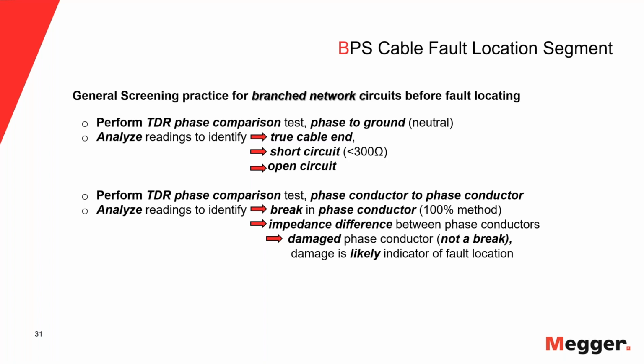So they tried it from one of the ends, but they were lucky because they were able to isolate and put the transformers in the open position. So they actually had 3 phases. So I said, okay, do an insulation resistance test. So they did it phase to ground, and every one was low. And then I said, well, do also the phase to phase. Everything was low. So I said, that is highly unusual that everything is low.